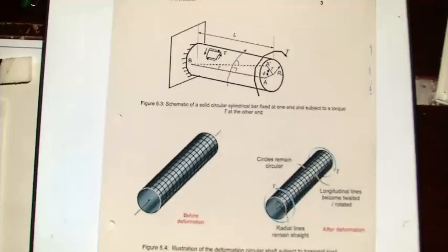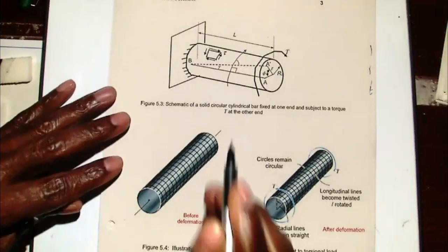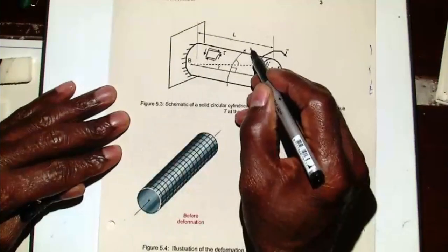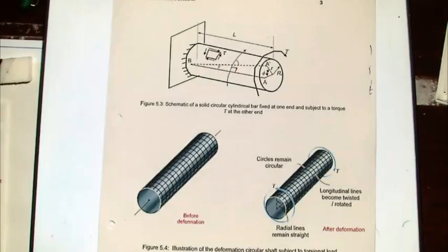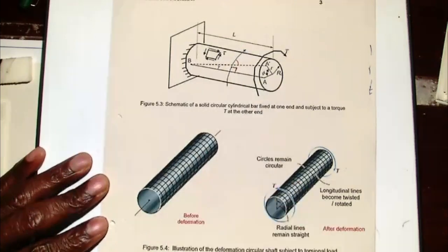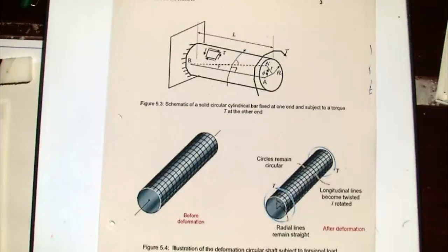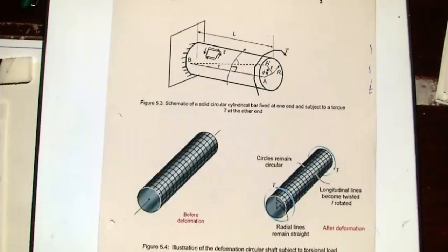So let's look at that small angle. If I have that initial line there and a circumferential line, it's very clear that the angle there will be 90 degrees, because the angle between a circumferential line and a line along the longitudinal axis is 90 degrees. If we now apply a torque to it, that line has moved to the one that is dashed. Therefore, the angle is no more 90. The angle is now less than 90, and it has decreased by that small amount gamma there.